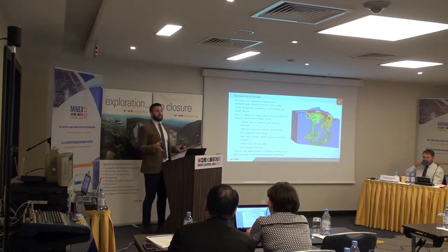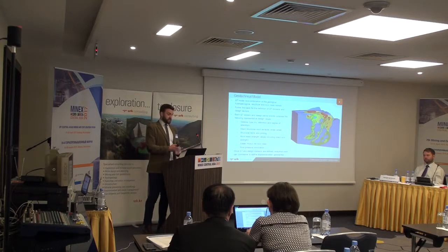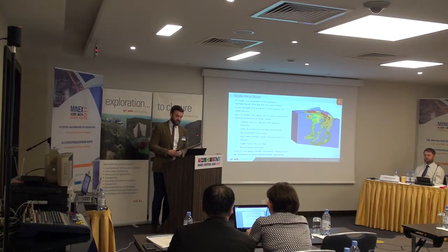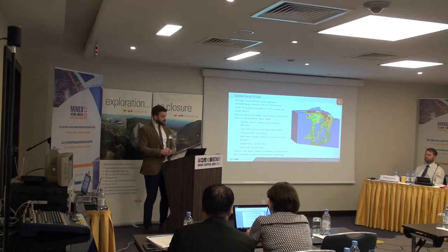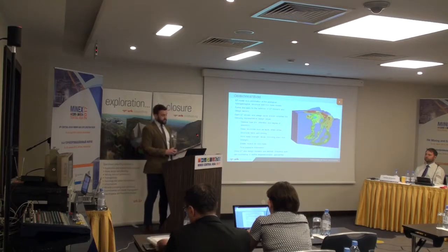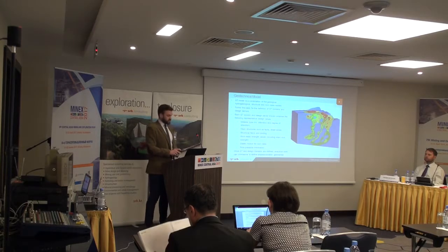So that's really the 4 elements, or 5 elements, to the geotechnical model. You have to have an understanding of the geology and the alteration, the hydrogeology, the major structures, and your rock mass model. And they really form the basis for defining your geotechnical domains. And the parameters you should assign to these geotechnical domains are listed here, and you should really understand the material type, the degree of alteration, major structures, any fabric or jointing, rock mass strength, your elastic modulus for your rock mass, and then also your pore pressure information. And these should be assigned to your different domains in your geotechnical model.